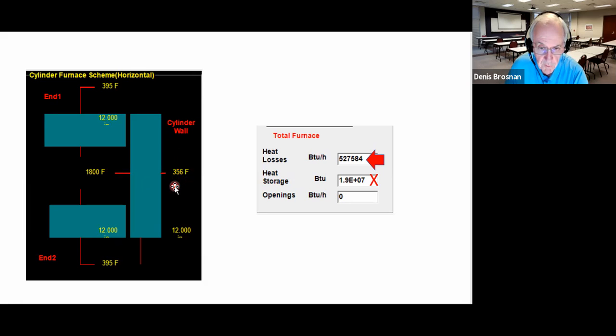Bricks fall out of rotary kiln linings from time to time, and people put high pressure air onto the kiln shell, air horns as they're called, to try to cool the shell to keep in operation as long as they can. The engineering of a brick lining for a kiln is very important, with keys and arches or wedges to make it the most stable lining.